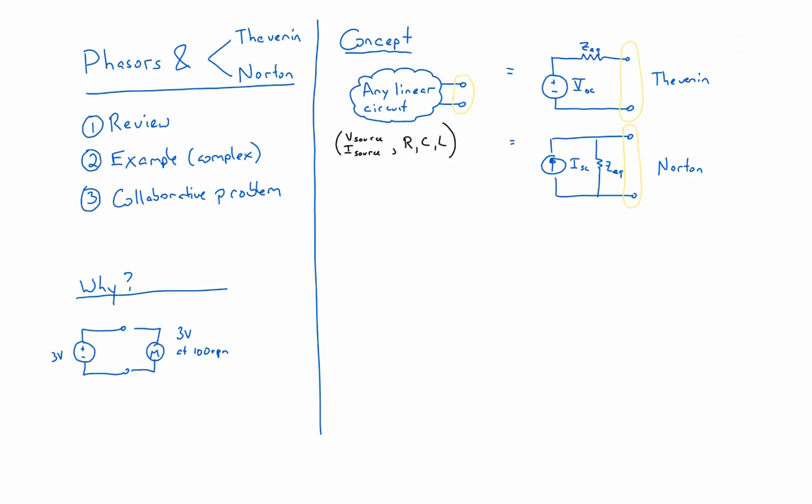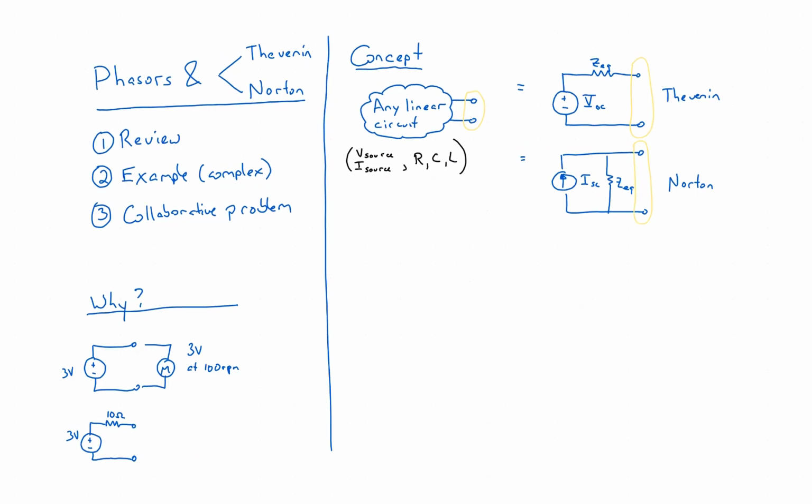If you had, you would discover that the 3-volt battery you were using only supplies 3 volts in an open circuit, but its true Thevenin equivalent looks like this. And that motor has a Thevenin equivalent too, and it looks like this. You might say, come on, a motor doesn't have a voltage source in it.